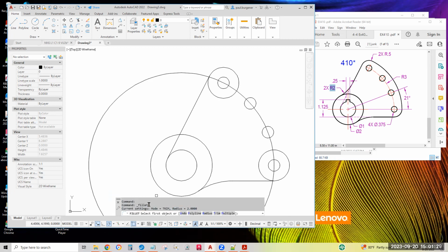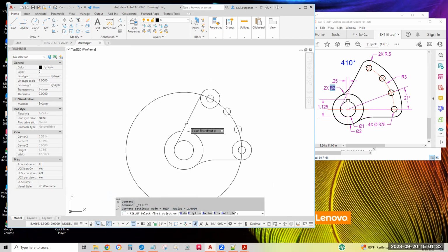I just go straight and select the first object. We'll click the line approximately where the fillet will hit. Could be out here, I suppose. And then click the circle where you expect the arc to touch. And why did it not work? All right, never noticed this before. Click fillet. I'm going to click outside the circle. There we go. Interesting. All these years I never noticed that.